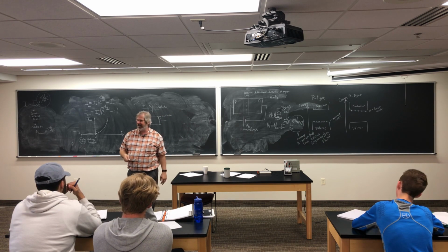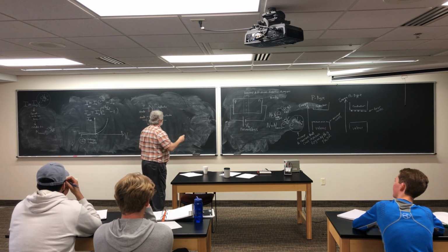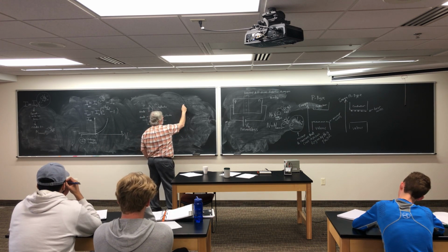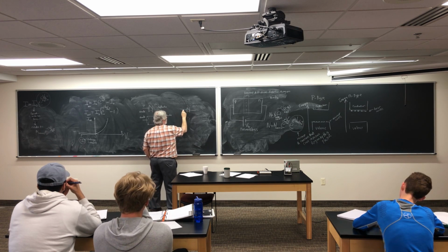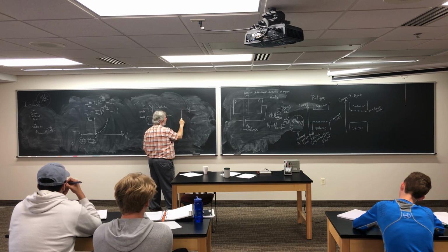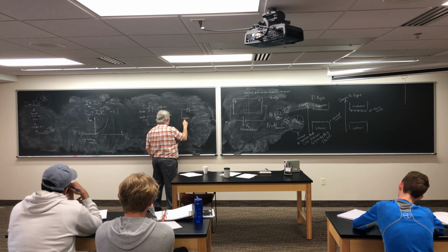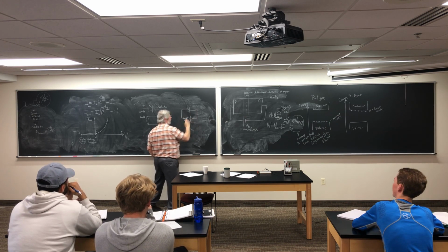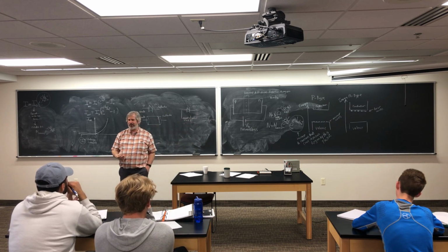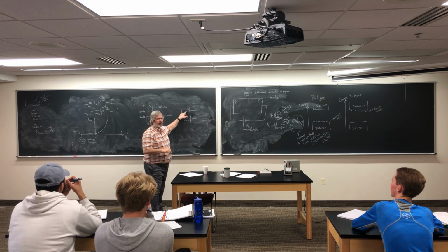And let's see how it changes as we change the bias voltage. Now usually, by the way, how I'm going to hook this up is I have my PN junction, I'm going to forward bias it, but I'm actually going to put a resistor in here, like a 270 ohm resistor, and then I'll put the positive and negative here. The reason you put that 270 ohm resistor in here is this thing has very little resistance.